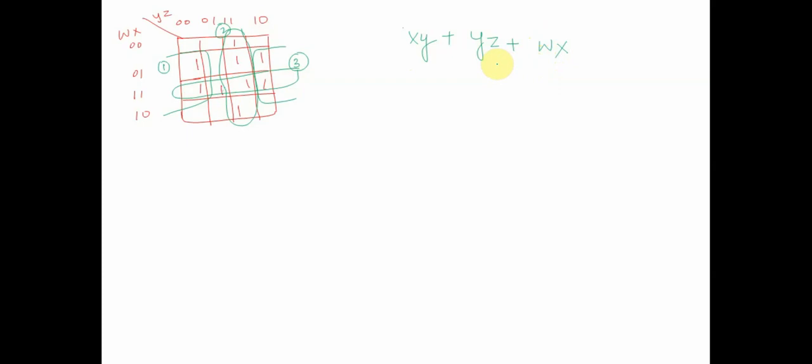Correct? Now this is one of the important concepts of implicants, essential prime implicants and prime implicants. Now I want to talk about something called don't cares. While we are trying to minimize our circuits, let's talk about don't cares. Don't cares simply mean these are unspecified outputs for certain inputs.